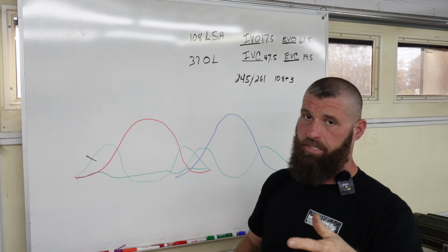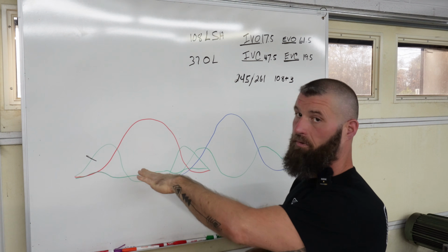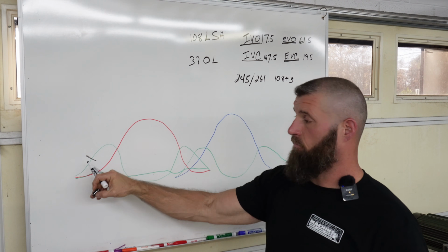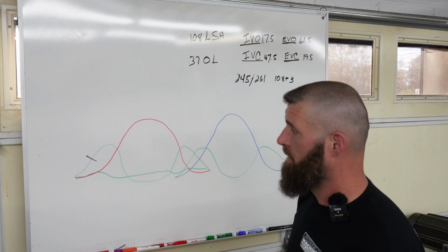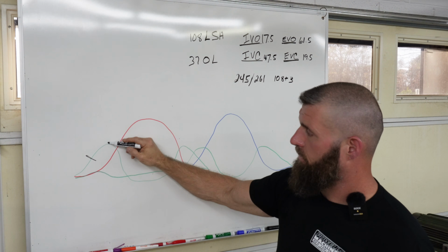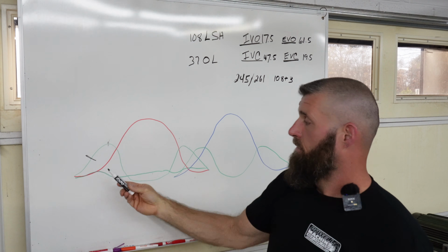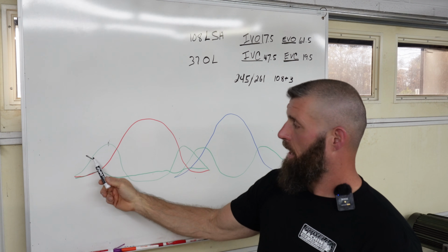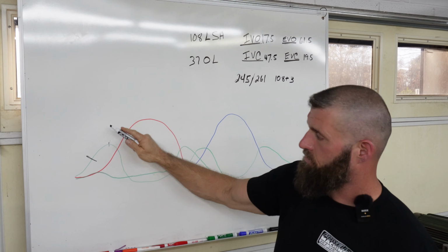That's where we say advertised. Well, we use 6 on all the data at the cam, but when we're designing lobes, we set all of our data at 4/1000ths tappet lift. So say from 4 to peak acceleration, as you shorten this up, that angle gets greater and greater.